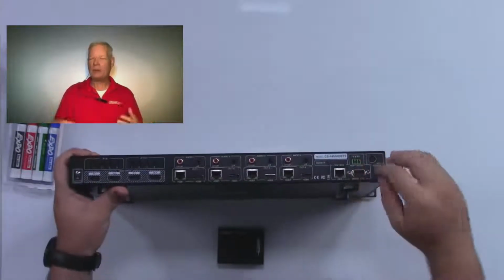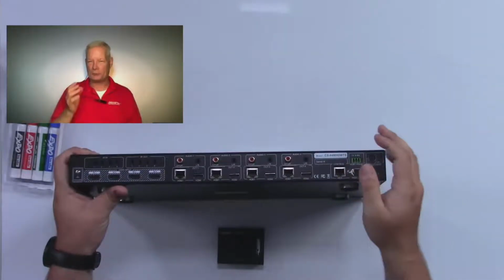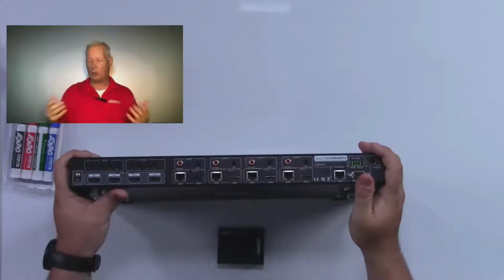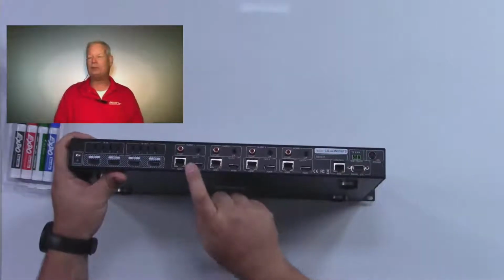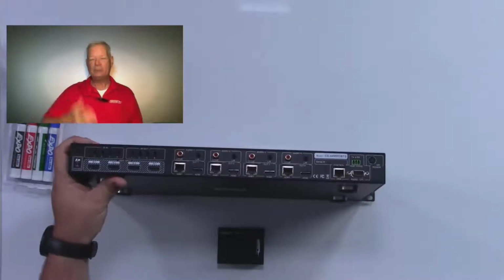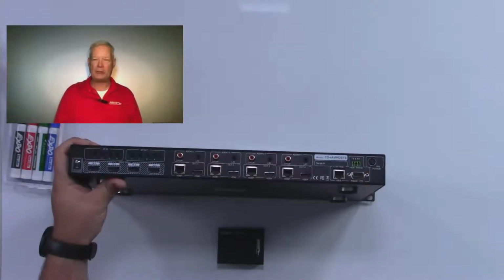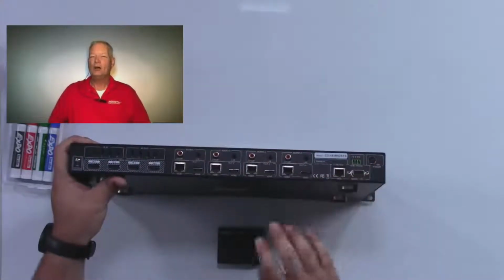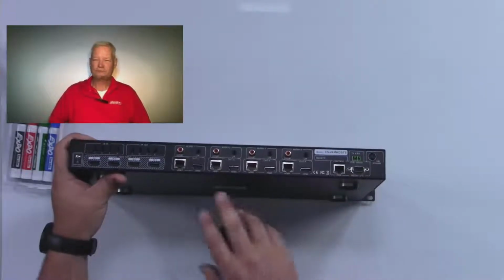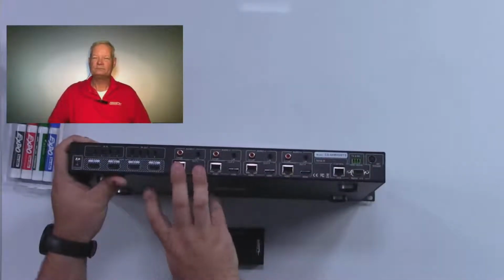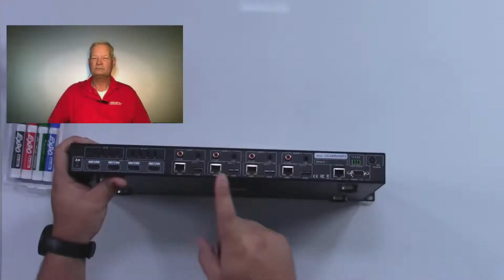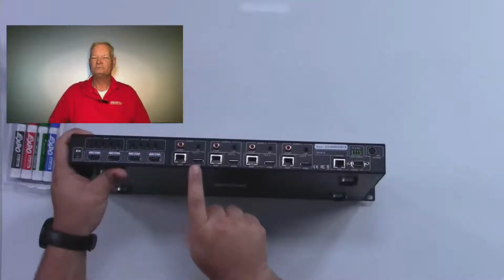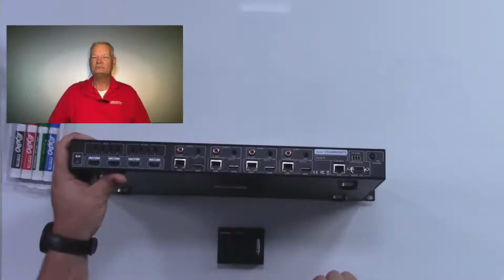The really nice thing about having the parallel or dual ports for each output, if you have an older AVR, for example, that might not be fully 4K compatible, you would put that locally to the rack on the HDMI output and your 4K display on the HDBaseT output. Right. And so you have all the connections you need right there. And you can also have a connection that's further away at the TV. You can use the HDBaseT. But then if you have an AVR inside the rack where the matrix is, you can simply loop out the HDMI output and go into your AVR.